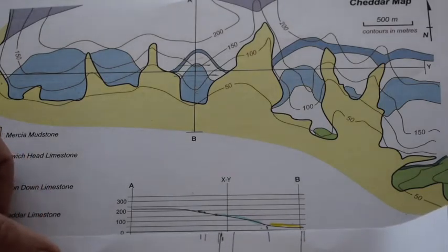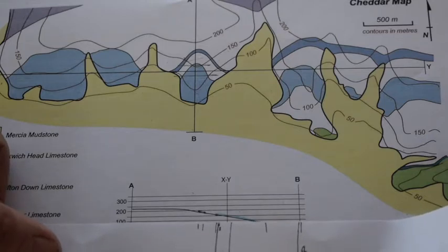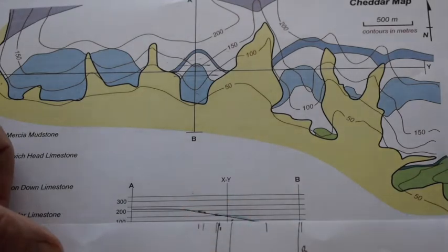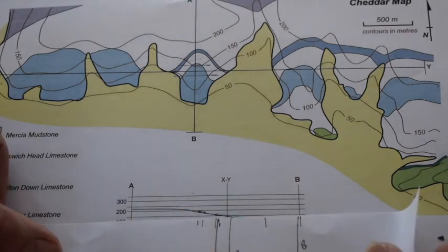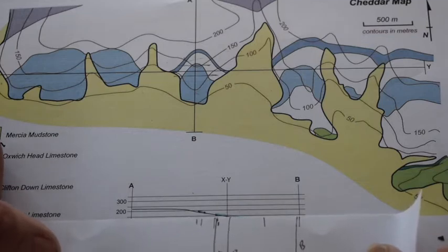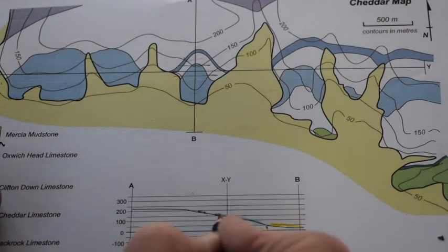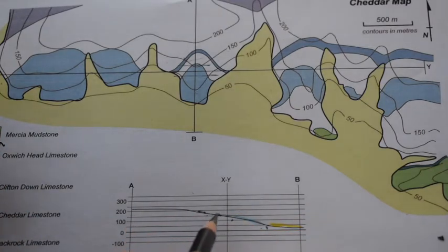So there's B, let's put the 100 contour on, so line up with the 100 elevation on our profile, and that's the 100 pick just there, and the 150, move up to here for the 150 pick, it's that line there, and it's just here, just behind the outcrop point. So we've got two places plus the outcrop on the boundary, join them up,